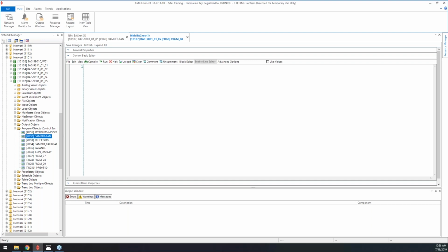So if we're going to do custom programming, maybe things like pick up an exhaust fan or point passing, we're going to say put that custom programming in program 7, 8, 9, 10. And again, group similar functions. So that exhaust fan logic may go in program 7, and then any point passing or off panel points, put those all together in program 8. The better you group your code, the easier it'll be to debug in the future.